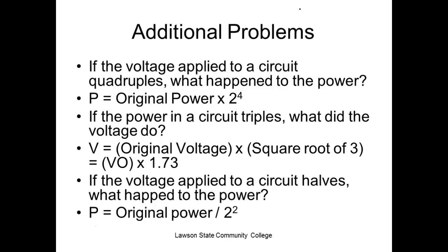What you got to understand though is you can't measure the impedance of a speaker with an ohm meter. It'll always measure less. So if you got an 8 ohm speaker, it's probably going to measure 4 or 5 ohms because that's an impedance. An impedance has to have a frequency on it, right? So 8 ohms would be at 1,000 hertz. Usually it always measures less, because that 8 ohms is an impedance. It's not a resistance, it's an impedance.